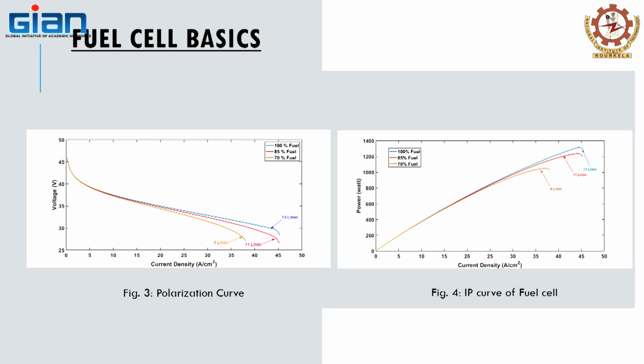which cannot be done by just having a fuel cell. The basic electrical engineering says that in order to extract maximum power from any source, you have to do impedance matching. That impedance matching you cannot do alone, you have to have some power converter. So using that power converter and the fuel cell, we can extract maximum power from the fuel cell.